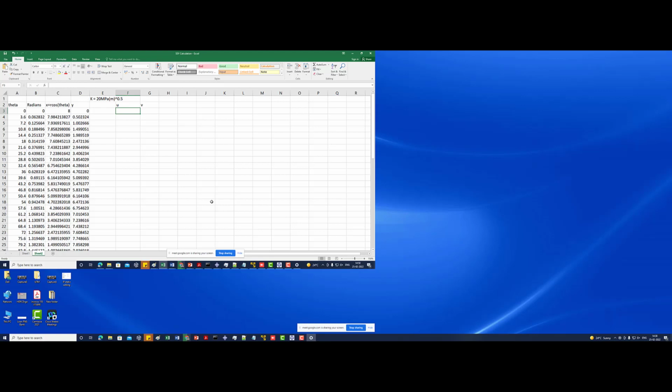So u is equal to K, which is the stress intensity factor, and we have to keep the dimensions in check, because that can create a lot of problems. The u which we will get here will be in meters, because our K is in MPa root meter and elastic modulus is in MPa, so that will have to be changed to millimeters at the end.